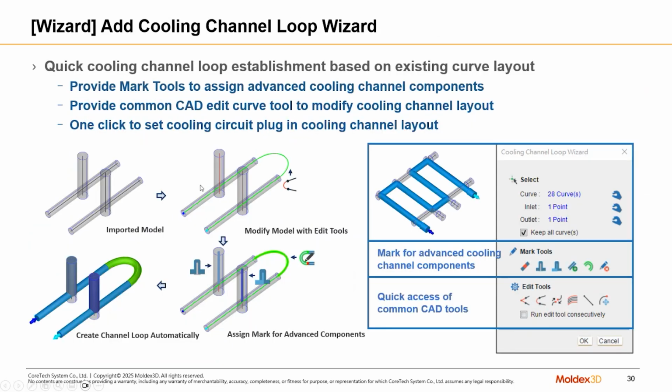All right, so a little bit more on the cooling channel extraction side. We also have a new cooling channel loop wizard that can help us to not only extract the channels, which we've already been able to do, but you can also use this tool to loop these channels together and create one continuous geometry or one continuous line of cooling channels, either with a bridging function or an intersect function or baffles, bubblers. All these sorts of things are available through this cooling channel loop wizard.